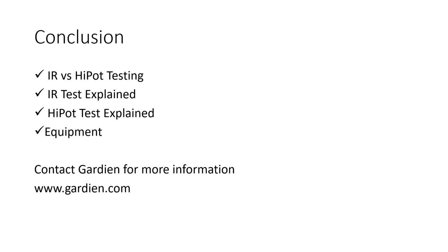And now that I mention it, the high voltage part of it, some people get confused between the IR and the Hipot, and then they say high voltage test. Well, when we talk about high voltage test in ET, a lot of times we're talking just higher voltage in the standard ET opens and shorts, where you're doing a voltage and an isolation and a continuity check all at once.